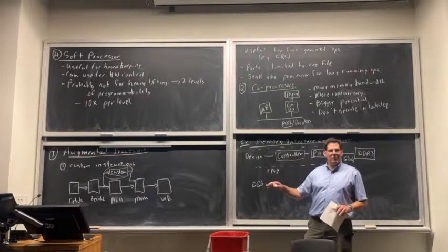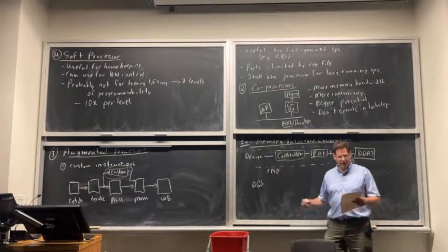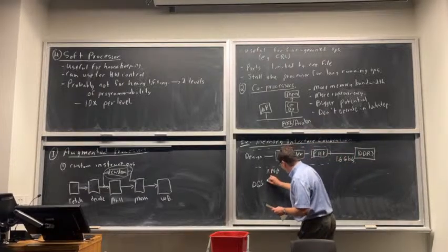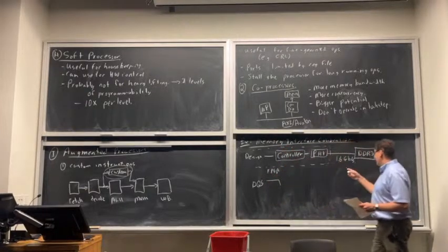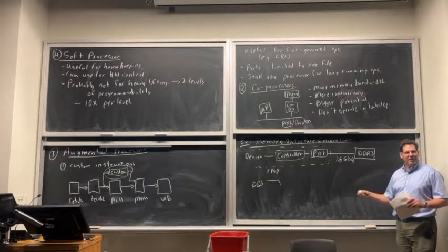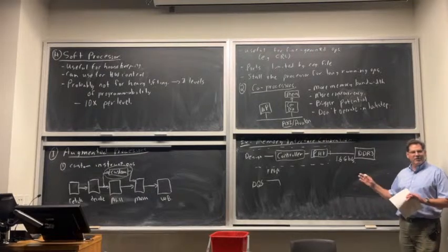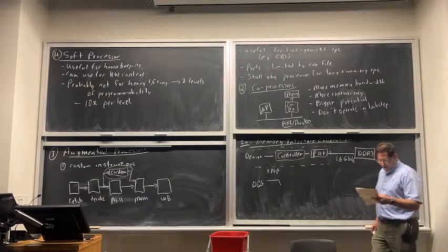Then one of the two major protocols that you use to send data at higher rates is called source synchronous. That's what all these memory interfaces use: DDR, GDDR, which is graphics DDR, is basically the same thing. RLDRAM is another variation on this, but they're all basically the same, and they're all source synchronous.